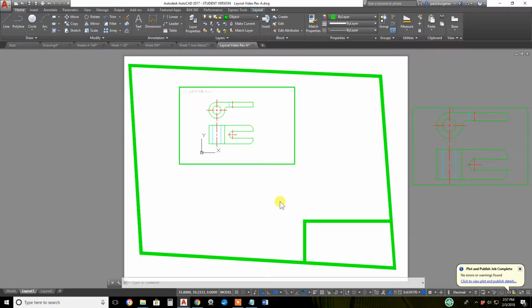Here we are continuing to talk about the layouts and viewports. Again, once you've clicked on a layout tab down here and created a rectangular viewport, you can double click within the viewport, as I already have. Notice you got the familiar XY coordinate from model space. The viewport becomes bold or dark, and the word model is down here on the command prompt.